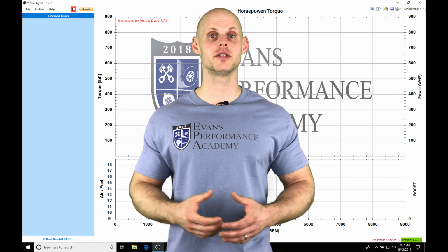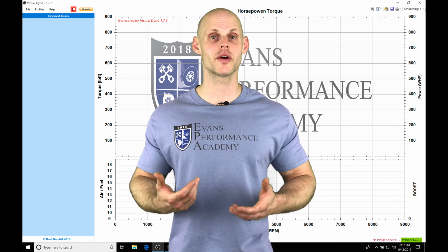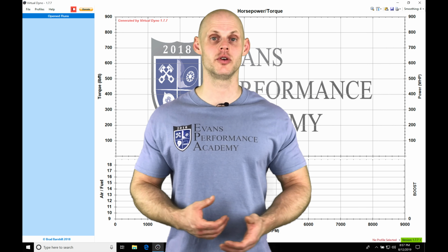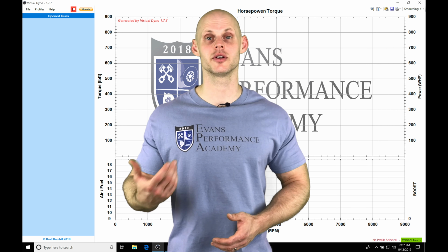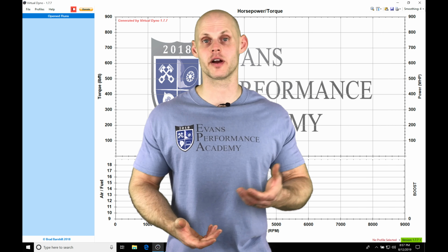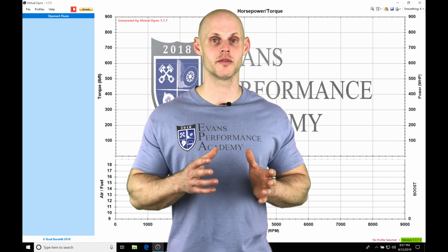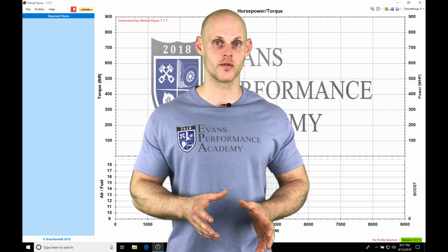Okay, so let's jump into this video and talk about working with our Virtual Dyno software in conjunction with our AEM Infinity. So when we're doing our tuning process with the Infinity, we're going to be capturing our data logs for full throttle tuning. We're going to be reviewing our fuel, our spark, our variable cam timing, our boost control, and many other parameters.